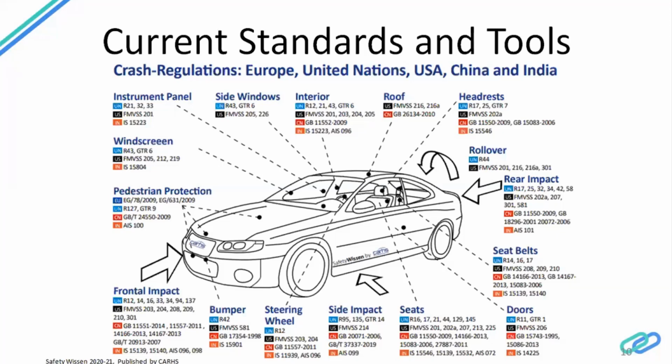a finite element model of a car will have millions of elements, and then you will add a dummy to it, the anthropometric testing device inside, and all that. It will increase the number of elements and nodes, and it will exponentially increase your processing time, etc. So it's even more important for you to understand these things in a virtual environment, and when you do it, it's extremely helpful. It helps the physical test.